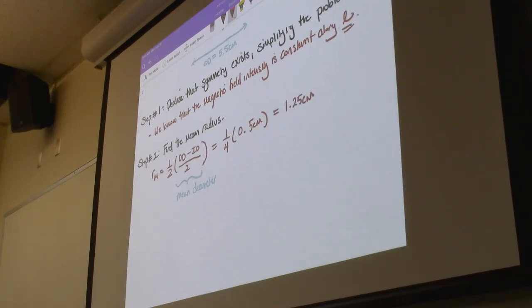And we also need to calculate the, yes? Wouldn't you want to add them if you wanted the average? Yeah, I'm sorry. That's true. I'm trying to compare what I did in the book and what I did in the notes, and I should just try to do it on my own. All right, let's start over here. We don't need to recalculate that value. So the mean radius was 1/2 outer diameter plus inner diameter divided by 2, which gave us 5.5 plus 5, so 10.5 divided by 2 will be 5.25.